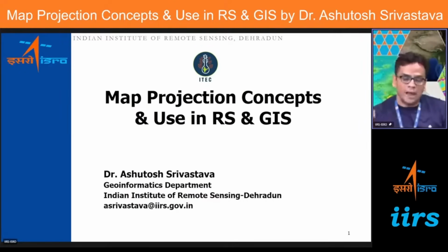Generally in all thematic maps, they write the scale and the north arrow. All this information will be there in that particular map. Okay, so that's how we come to know in which projection system or coordinate system this map is. And whenever satellite images are there, as per our requirement, we can transform one projection system to another projection system.